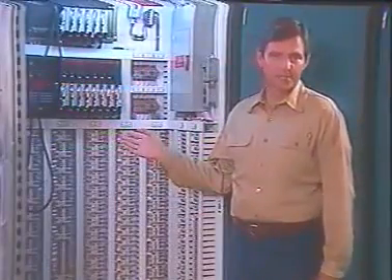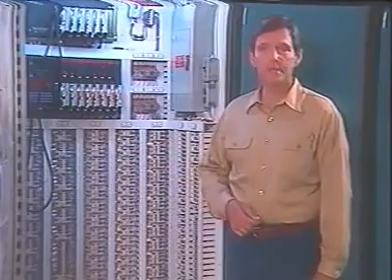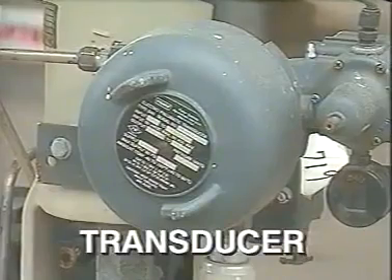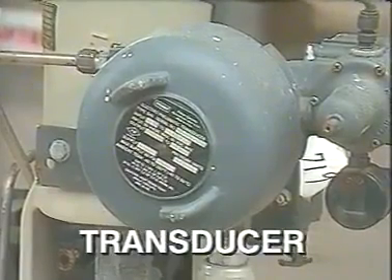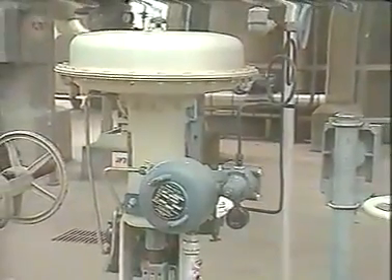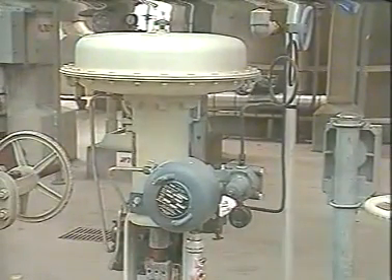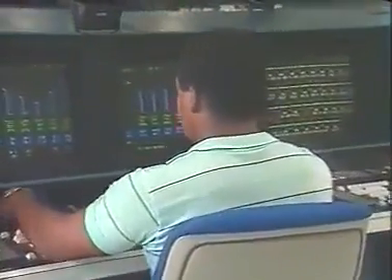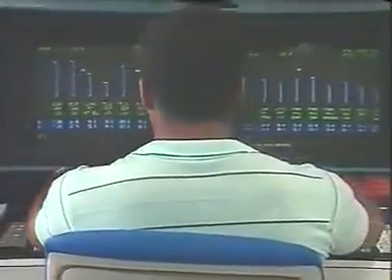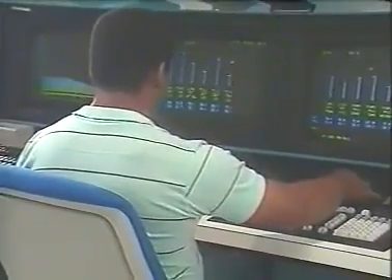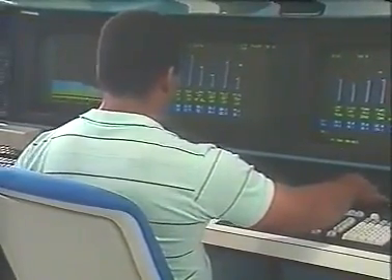Even when electrical transmission is used, valves and some system instruments are usually still activated by compressed air. To convert electrical signals to compressed air, we use a device called a transducer. Transducers allow us to tie electrical and pneumatic transmission systems together. The trend in process instrumentation is towards more electronics. That's because electrical transmission systems are generally more accurate and can more easily interface with computers.